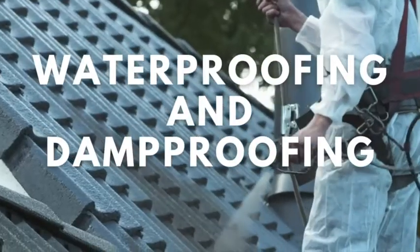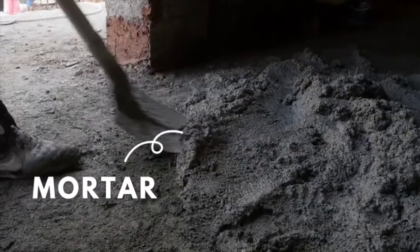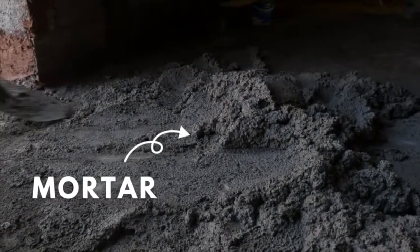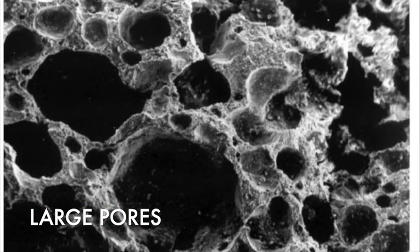Waterproofing and damp proofing. In waterproofing of concrete, a mortar or concrete is considered impermeable when it does not permit passage or flow of water through its pores or voids. The absorption of a mortar or concrete is the property of drawing in or engrossing water into pores or voids by capillary action. If the pores or voids between particles are sufficiently large and connected from surface to surface of the wall, the concrete will be permeable to water.